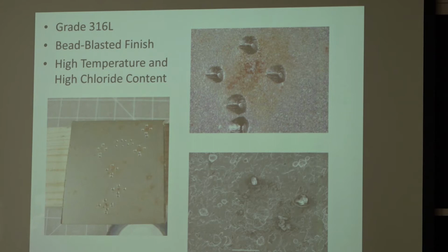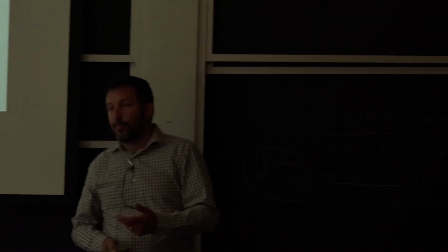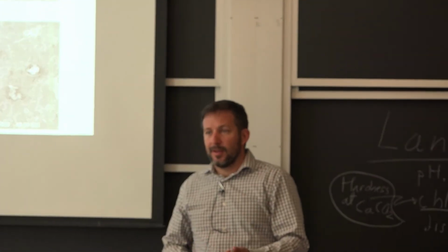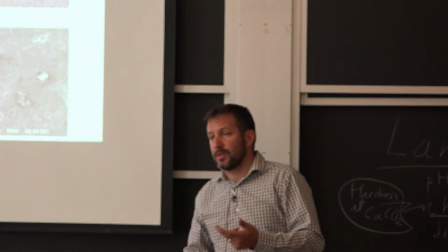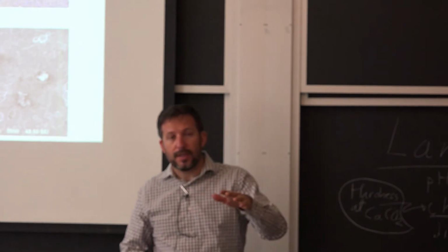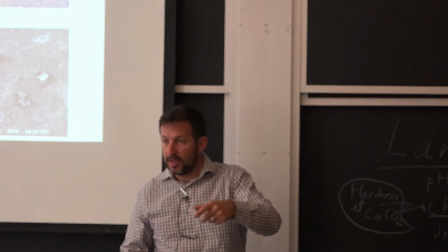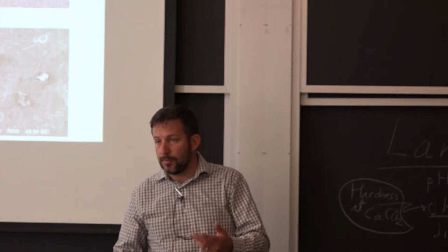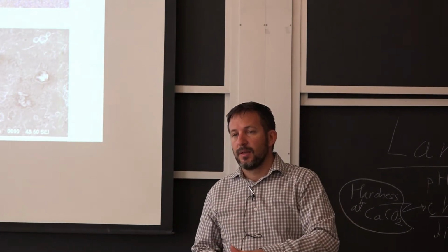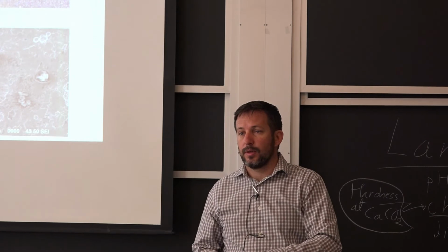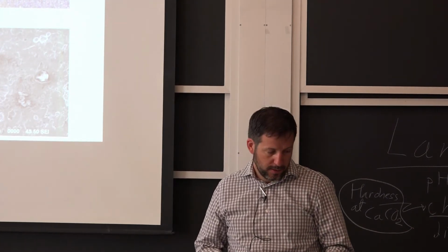I guess one simple way to look at it, if you think of titanium, aluminum, and copper, they look good naturally, right? You put a little water on it and they look fine. They all have a stable protective layer on them. Therefore, they are all at risk for pitting corrosion because you have to perforate through that protective film, and when you do, it's at one spot, and then you have more risk of pitting than you do on a piece of steel. You only get really bad pitting on steel if there's a specific condition there that you have coal tar or a different soil condition like we saw with the tank.